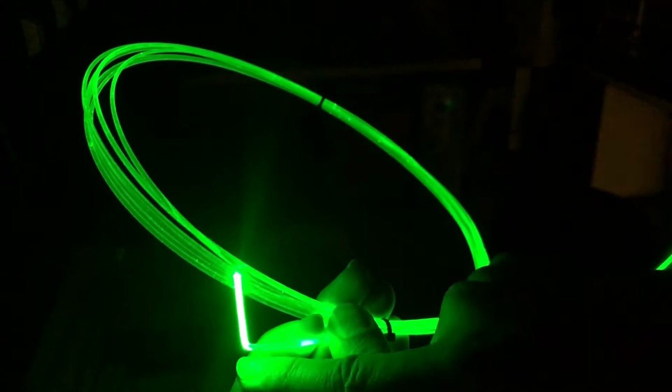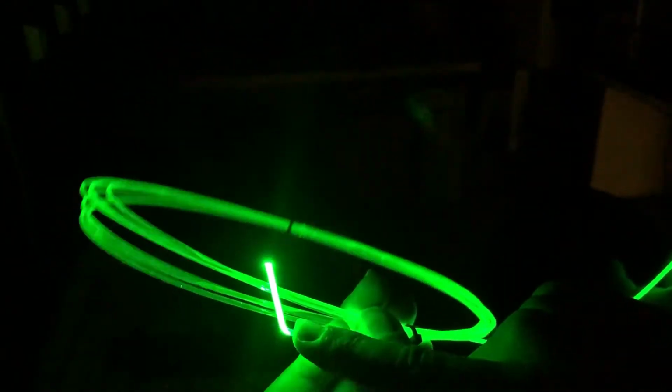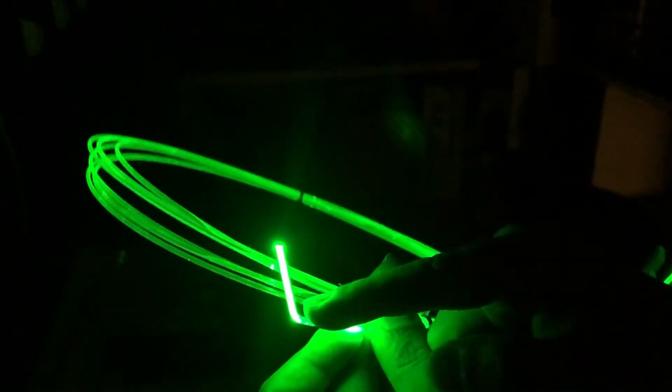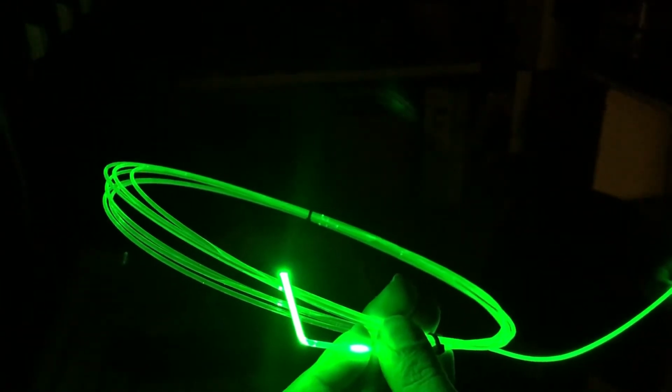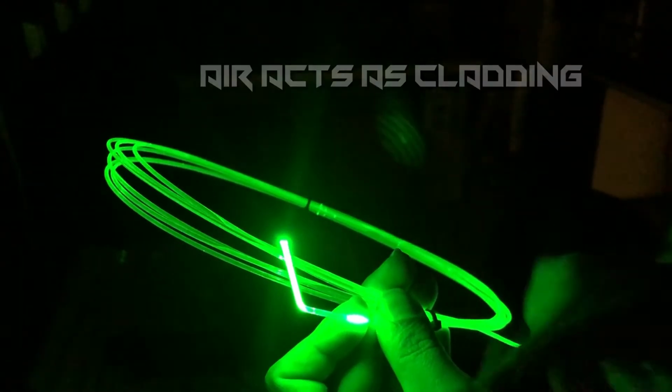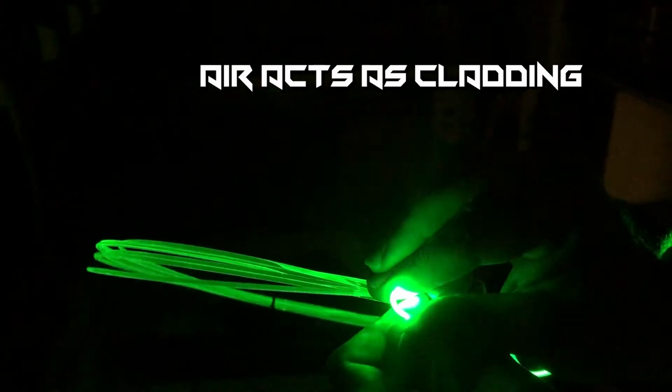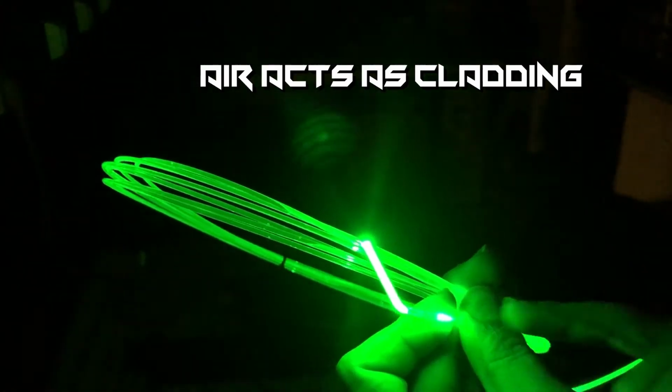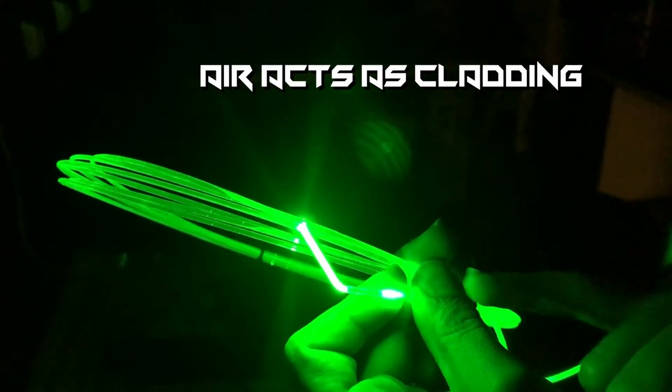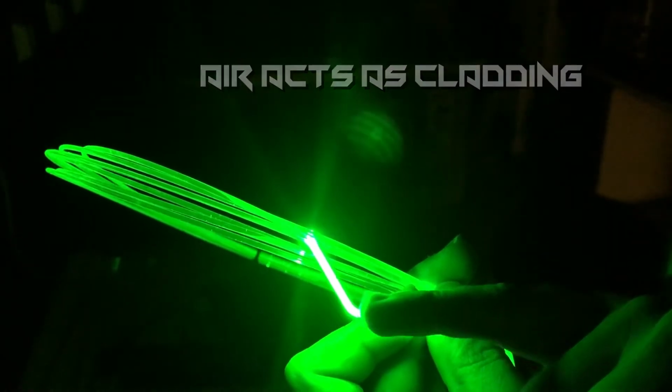Also, these are highly affected by attenuation factor, meaning there is absorption by the fiber itself. However, this is only critical in long-distance communication. This fiber does not have cladding, but with the material's refraction index being approximately 1.4, the air itself around the fiber works as cladding, having the wave-guiding effect.